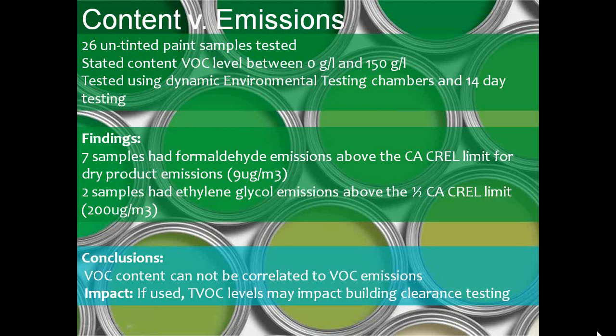So the other real impact in this is that, especially for these facility managers, it can cause a real problem for the TVOC, or total VOC levels, in your building. Here's an example. People who are building a high-performance building will decide, we're going to use this low VOC paint. But unfortunately, it's only low VOC content paint.